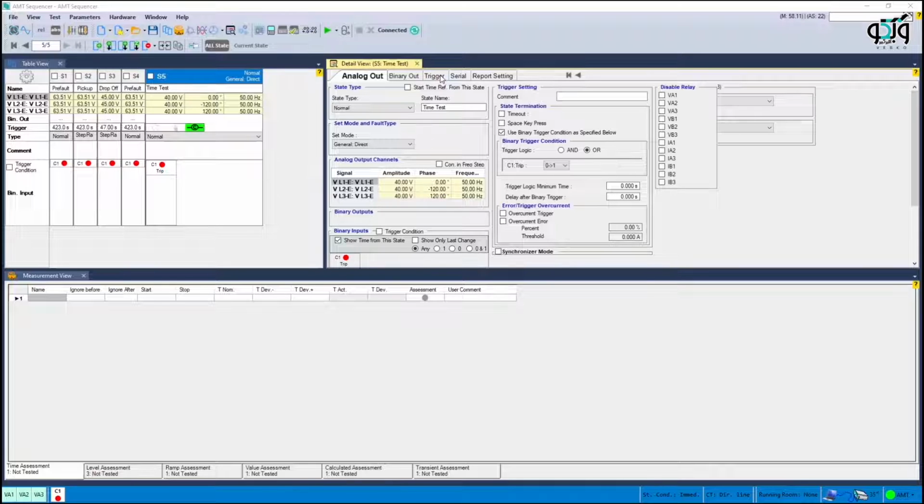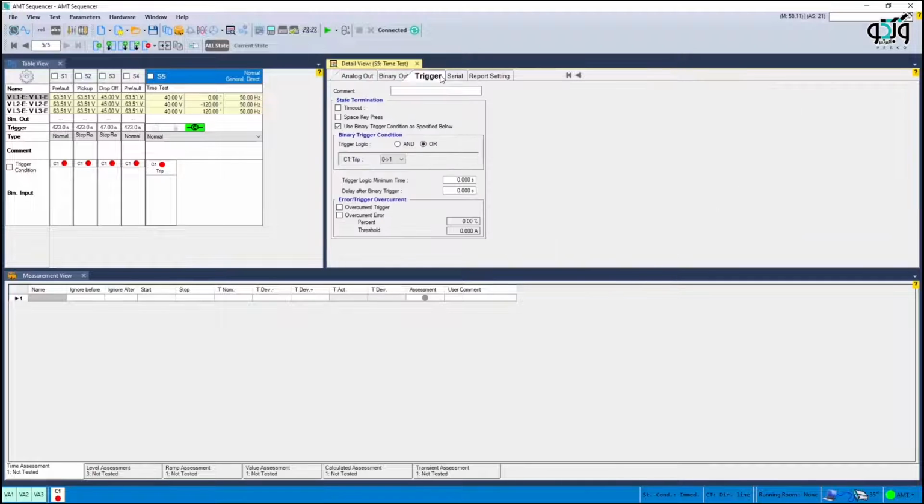This state trigger can also be the relay tripping contact, which is assigned to one of the binary inputs by default. Or it can be recorded by pressing a space when it sees the relay LED. However, due to the high accuracy, it's recommended to use binary status change.